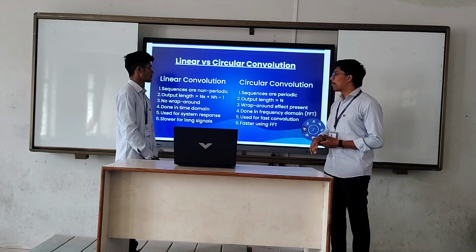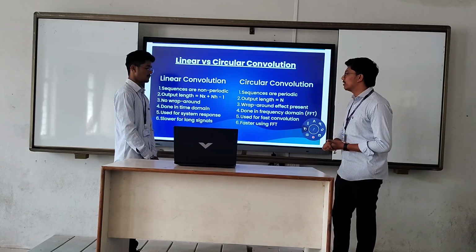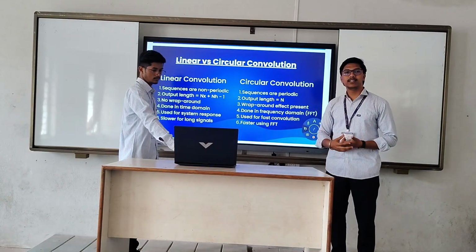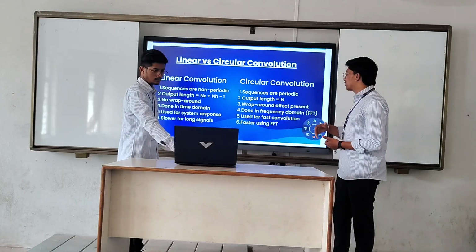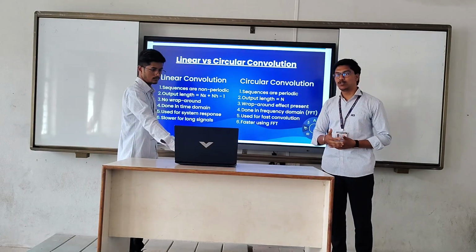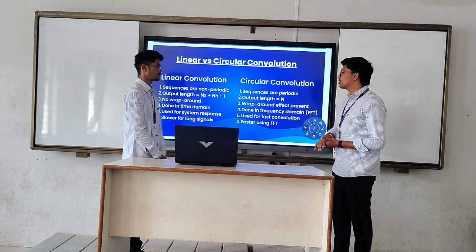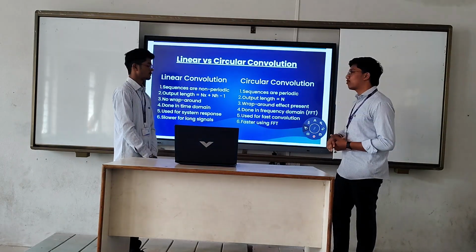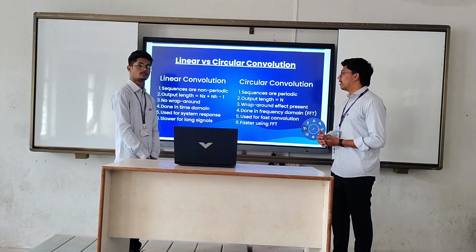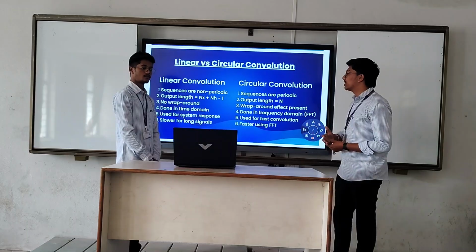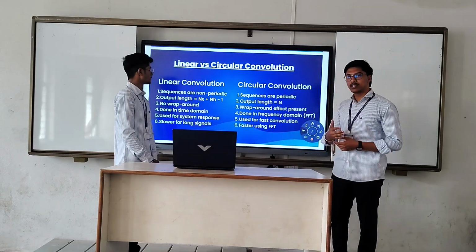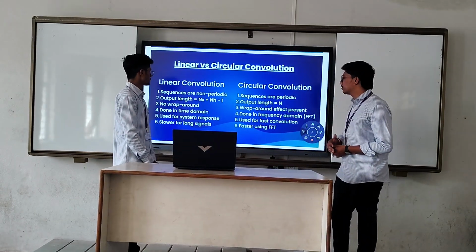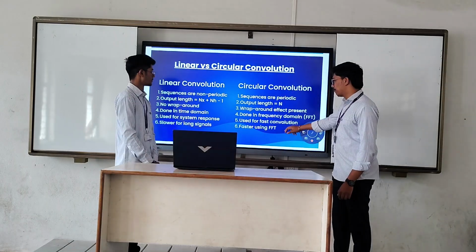Linear convolution is done in the time domain, and circular convolution in the frequency domain. So linear convolution is used for system response, and circular convolution is used for fast convolution. Linear convolution is slower for long signals, and circular convolution is faster and used effectively.